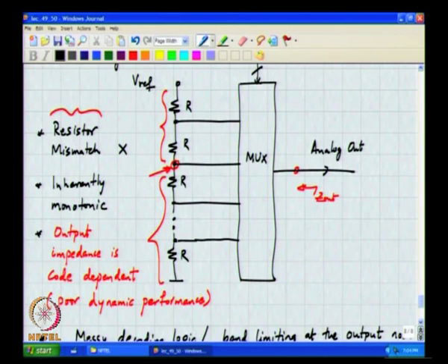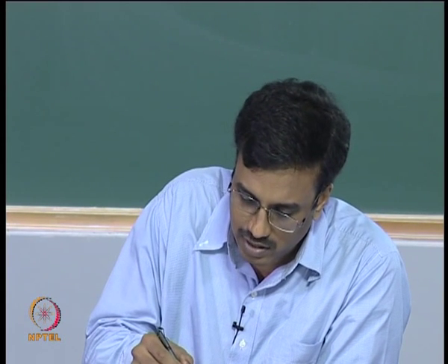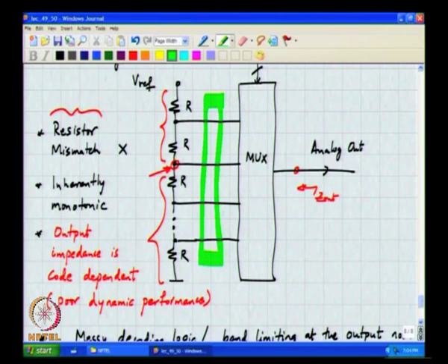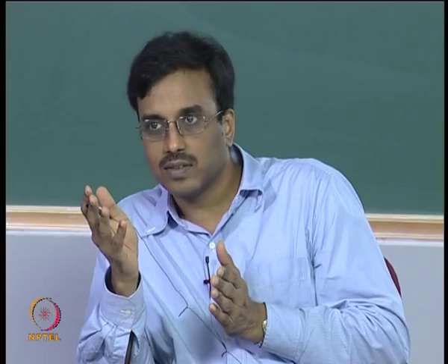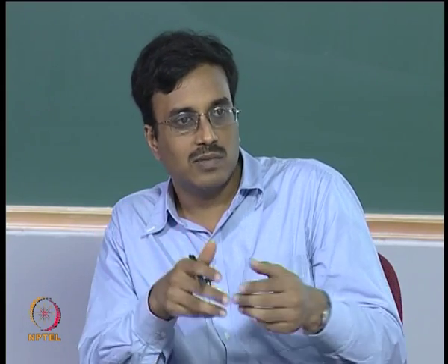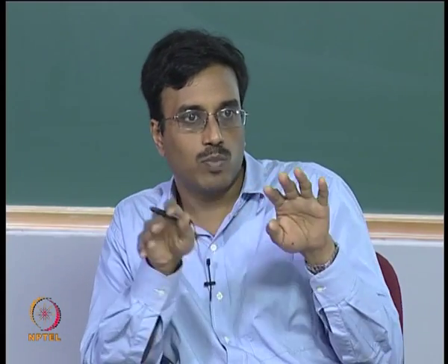A resistor string, if you think about it in another light, you can think of as a DAC where all the outputs are available simultaneously and you pick which one you want, that is what the mux is doing. So, when you had a flash array where all the references were needed at once, this seems like a natural choice, since this resistor string has got all DAC outputs